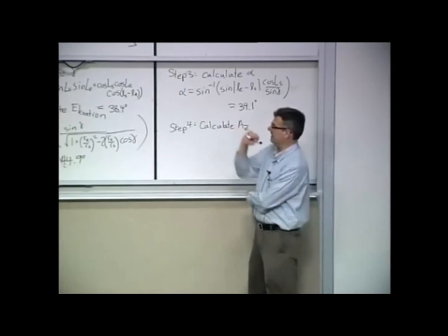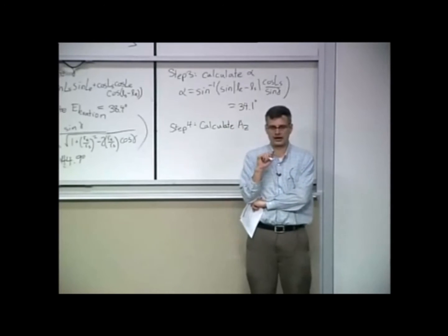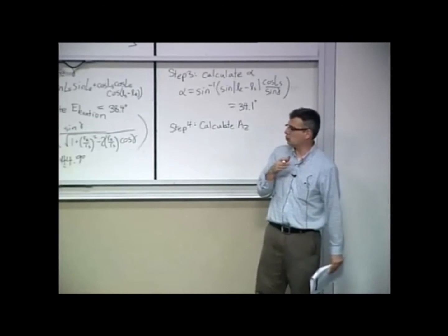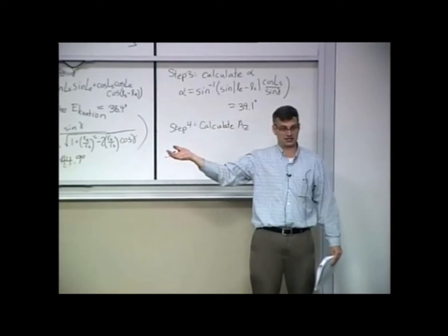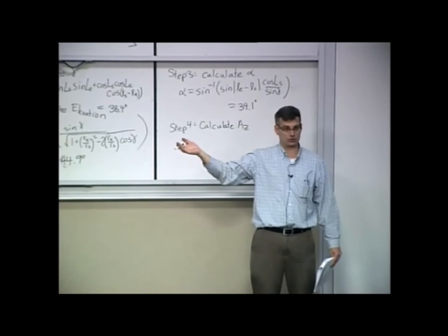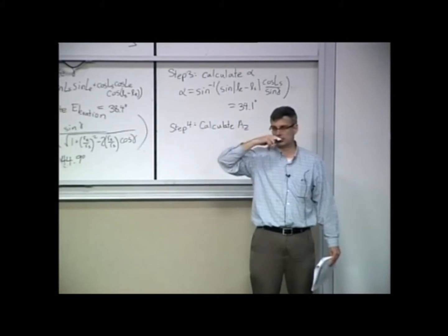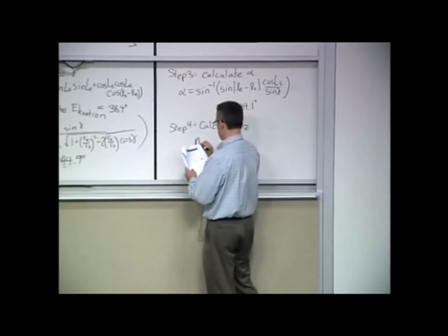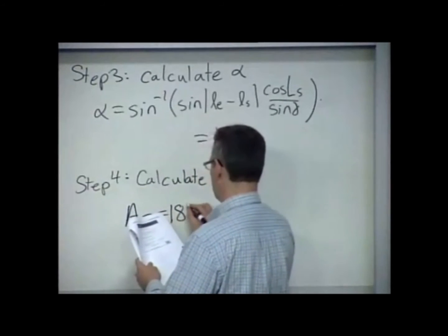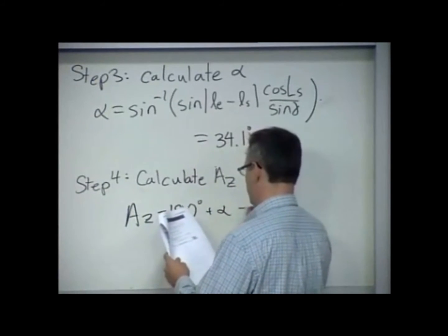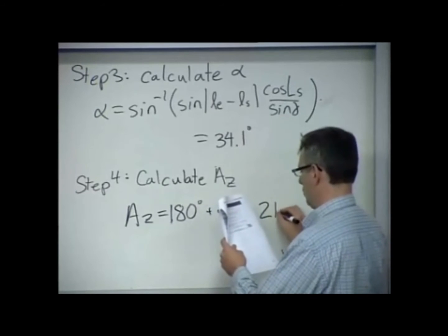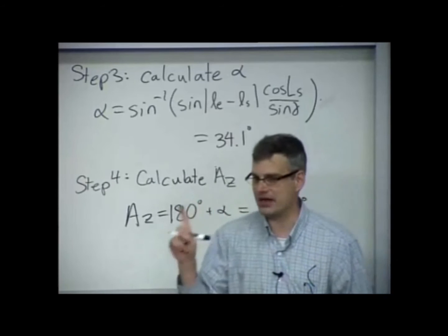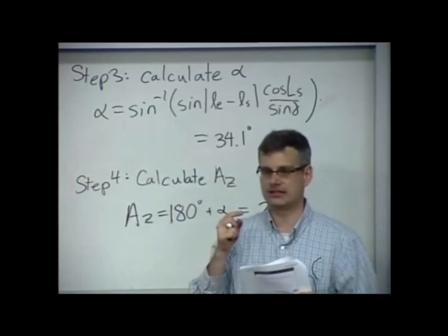And if Atlanta is at minus 84 and the longitude is at minus 105, this is also about 20 degrees west of us, where we're standing right now, more or less, in longitude. And so I would say this is southwest. So based on that contingency, I need to add 180 degrees to alpha, giving me 214.1 degrees of azimuth, as measured from the north, clockwise.